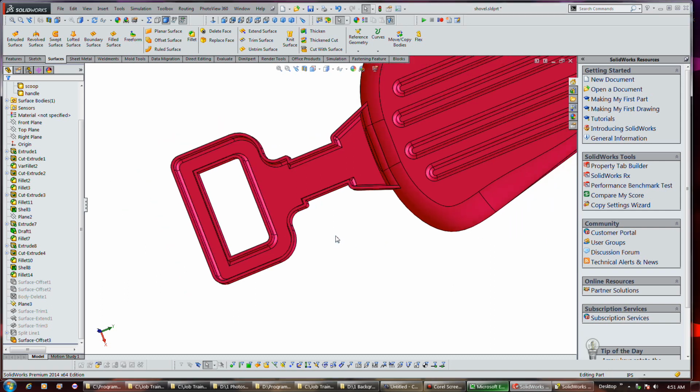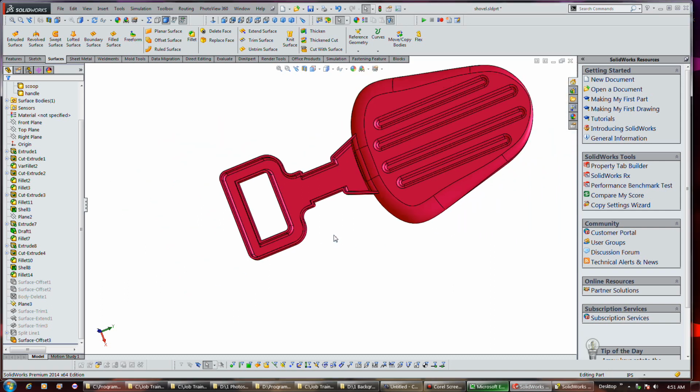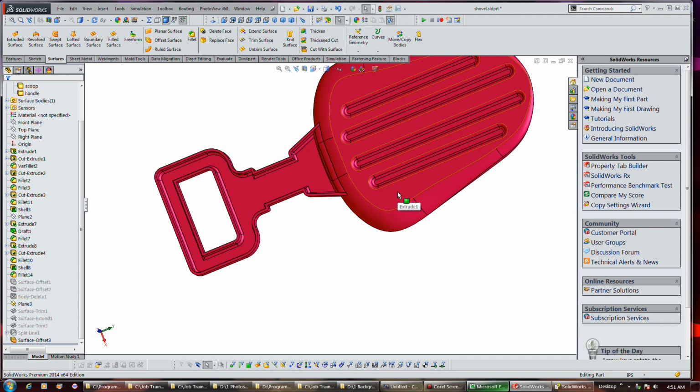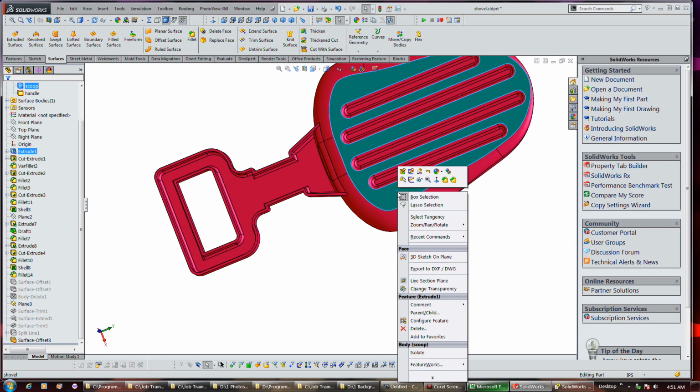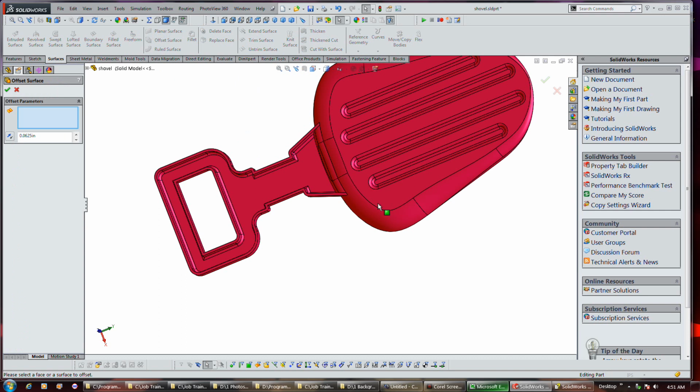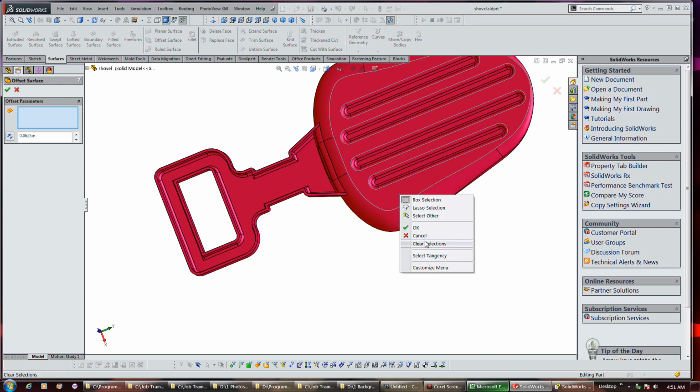Okay, now when you're working with sheet metal and thin parts, you can simulate them, but apparently it's still usually better to convert it to a shell and simulate that because it'll be a lot simpler. If you think about it, usually the thickness of a thin part isn't always relevant in most simulations. How you do this is, you just work with your surface commands. In fact, we're not going to be dealing with the simulator in this lesson at all.